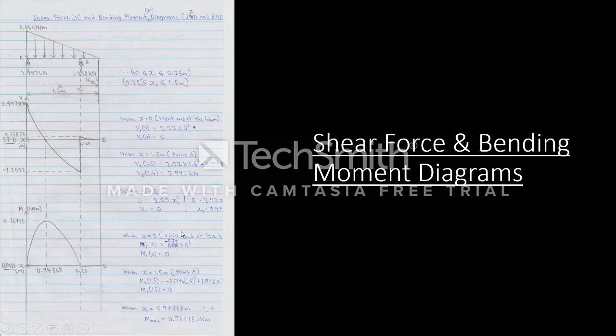Next, using these functions, I was able to construct the shear force diagram, which is right here, and also the bending moment diagram, which is right here. Using these graphs, I was able to find the maximum shear force, 2.997 kilonewtons, and the maximum bending moment, 0.76415 kilonewton meters.